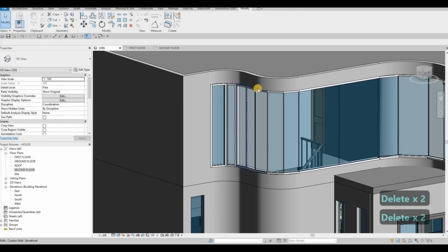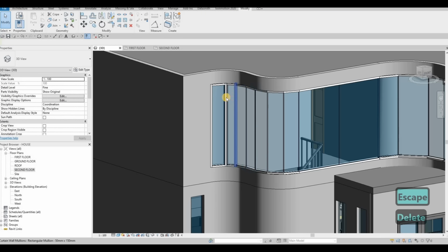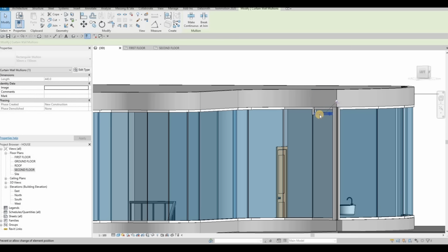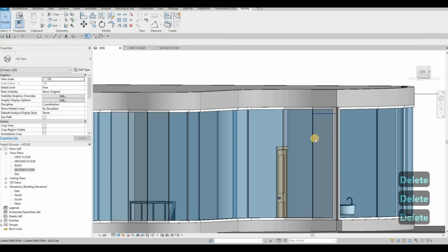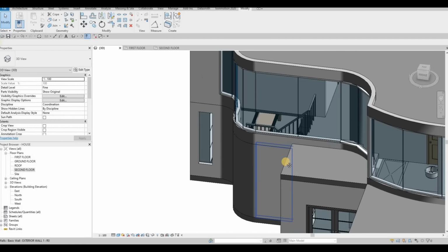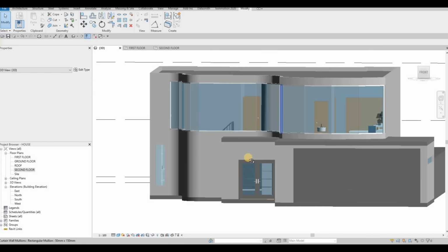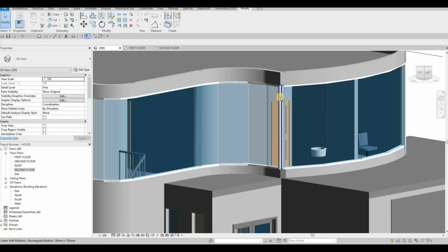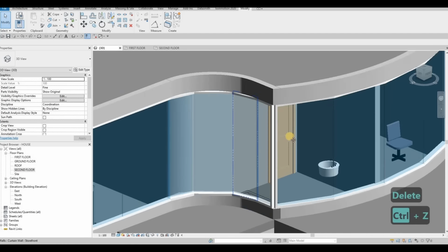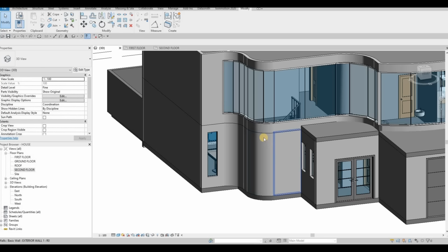When I showed you to just select all of the mullions and then unpin them so that it's easier for you to delete, you don't need to do it individually. So now this one looks much better. And then of course this one needs to be deleted. Anything that is not nice there. So as you can see, at least it has its continuous look now that we're going over. Of course at the corner it's not possible, so might as well just leave it like there so that we have that breakage. And then here we're going to do the same thing.